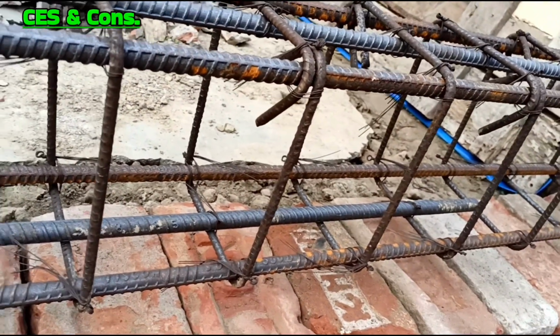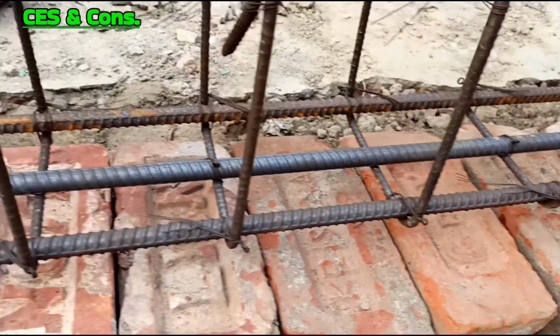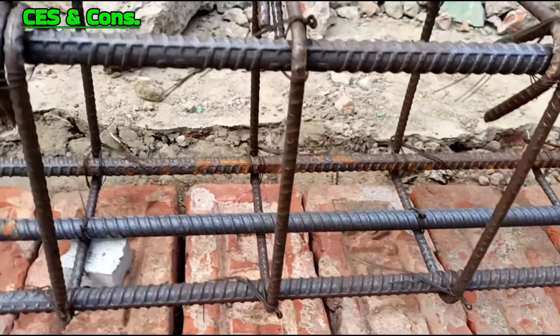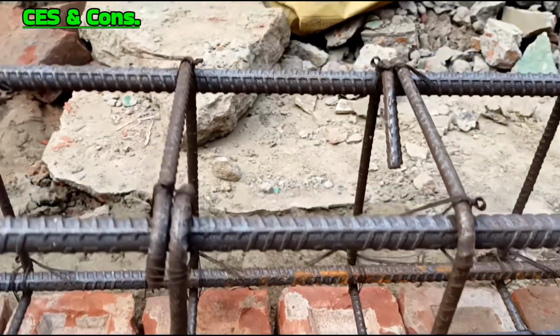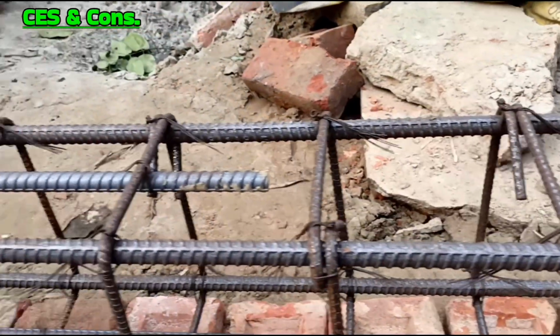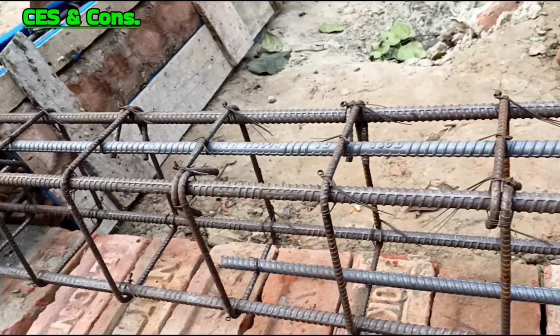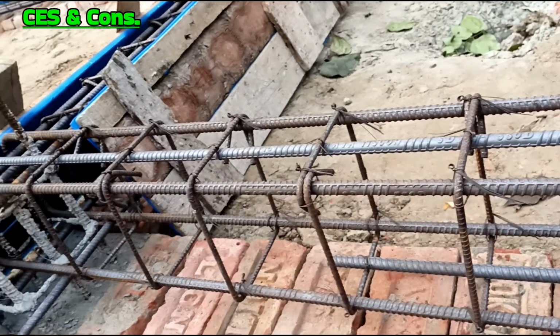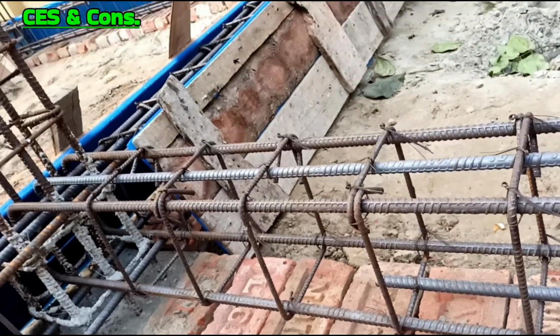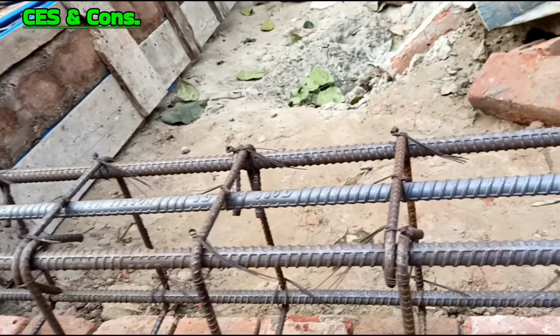Therefore, we have to provide the longitudinal main reinforcement of the beam at bottom of the beam. In addition to this, we have to provide main reinforcement at top also near the two supports. This may be curtailed as short pieces. Friends, see in the video that we have provided 3 number 16 mm dia longitudinal main bars at bottom of the beam to handle the sagging bending moment.